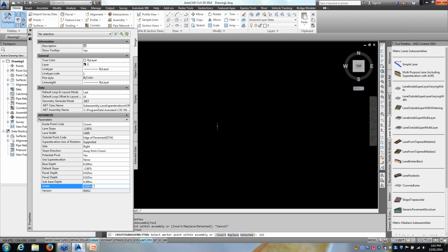Alright, my machine hasn't done this for a while, and maybe it's actually the GoToMeeting thing. If you're ever trying to select these things and they select and then unhighlight, like those ones are doing now, flashing blue and then disappearing, simply save your drawing and restart Civil 3D, that fixes it up. In this case that's not an option for me, so I'm going to actually place it in here.